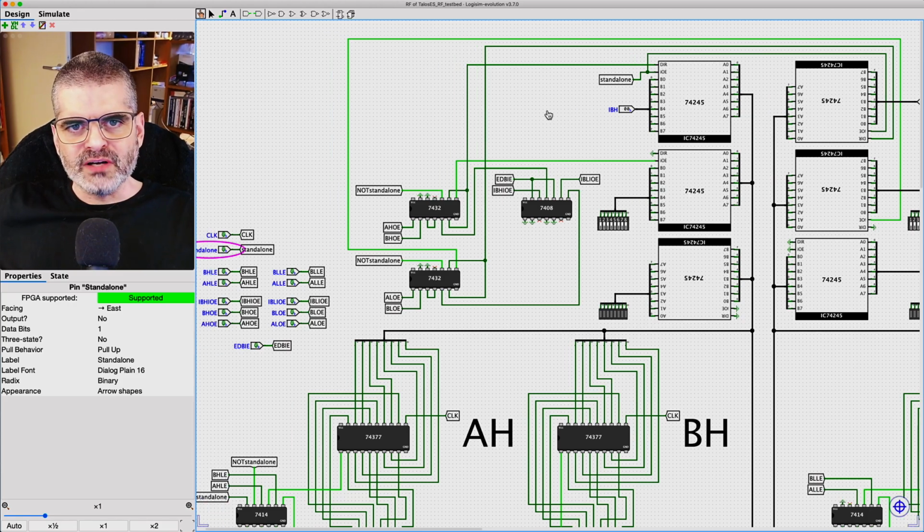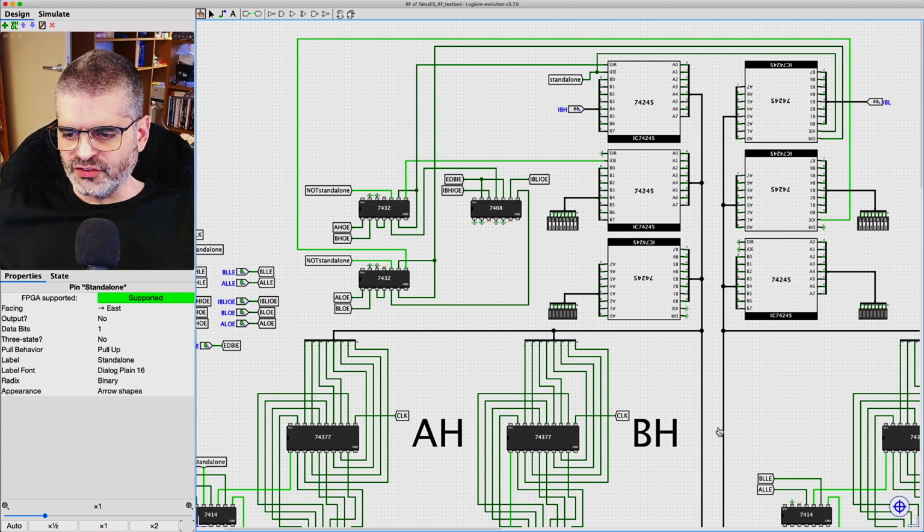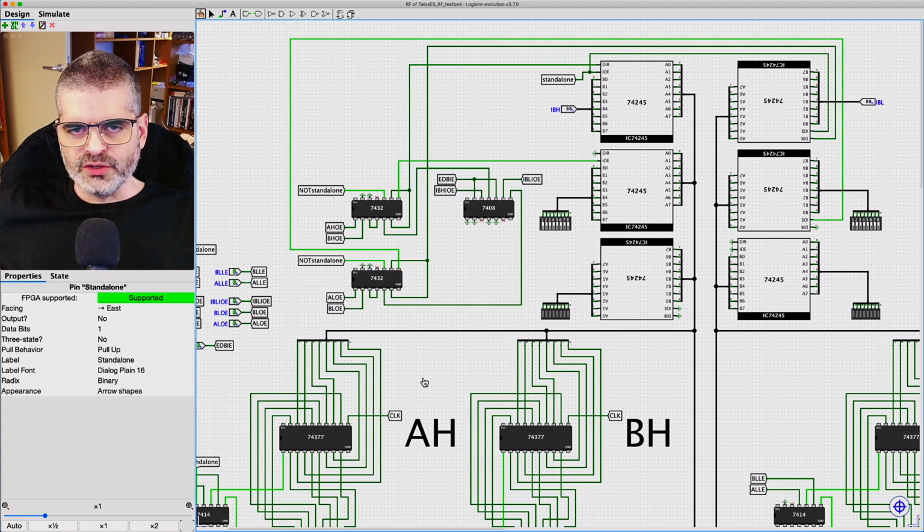What happens, however, if one of these registers here, one of the 4 registers, wants to drive the internal local bus, wants to put a value on the bus? If this would still be trying to drive the bus from the outside in, we would have a conflict.